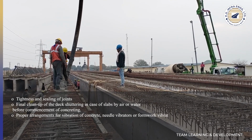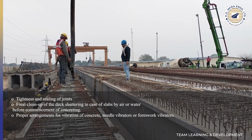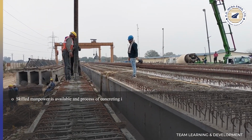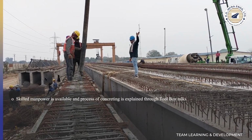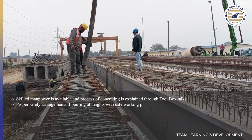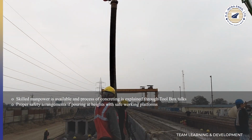Proper arrangement for vibration of concrete, needle vibrators, form work vibrators as per the site condition. Skilled manpower is available and process of concreting is explained through toolbox talk with the workers. Proper safety arrangements if pouring at heights with a safe working platform.